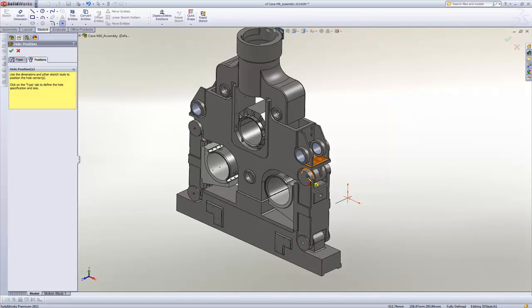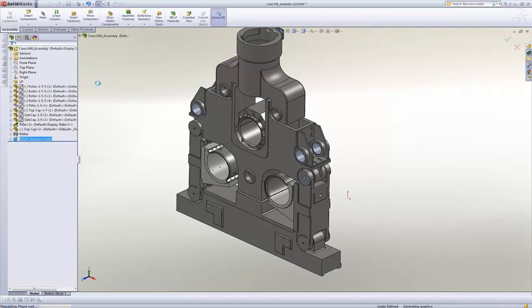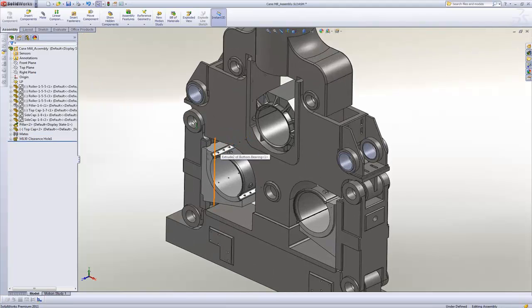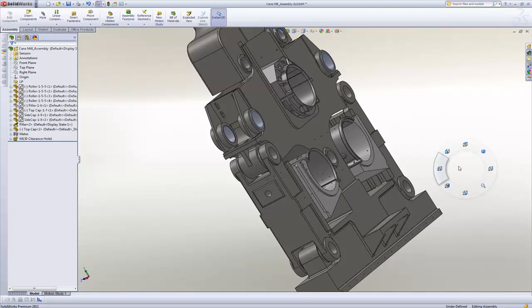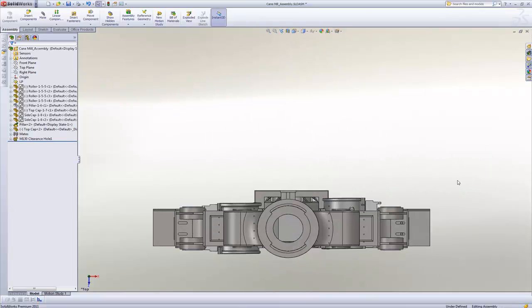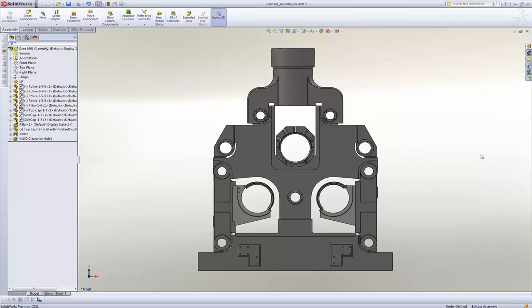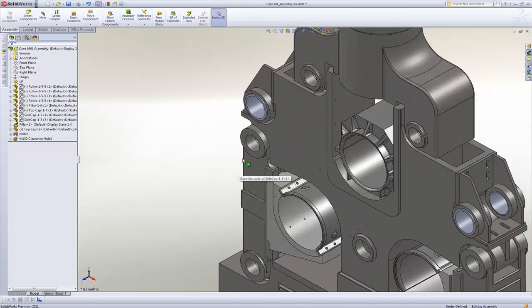To drill a hole at the center, you just need to go closer to the curve or the circular edge. It automatically gives you the center point snap. You want to drill the hole at the center, just pick the center. Mouse gesture gives access to 8 of the most commonly used commands and is an example of SolidWorks' intuitive and innovative user interface.